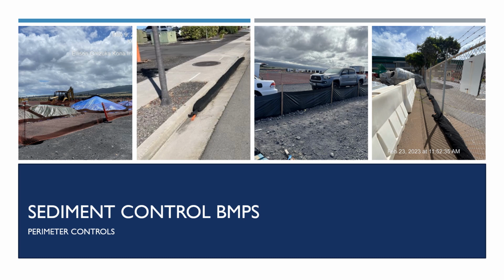Preventing sediment from leaving the site can look different depending on the site's features and scheduled work. Perimeter controls are a type of sediment control placed along the downslope perimeter of a disturbed area. Perimeter controls capture sediment, debris, and other potential pollutants that have been entrained in stormwater runoff. This means there may be sediment and debris accumulation on the upgradient side of these BMPs that must be removed as routine maintenance. In locations that are at risk of wind erosion, such as material stockpiles or disturbed ground, dust screens can be utilized in addition to sediment control measures along the perimeter of a site.